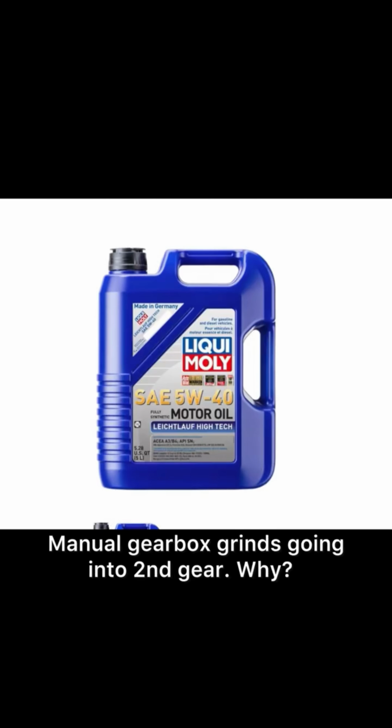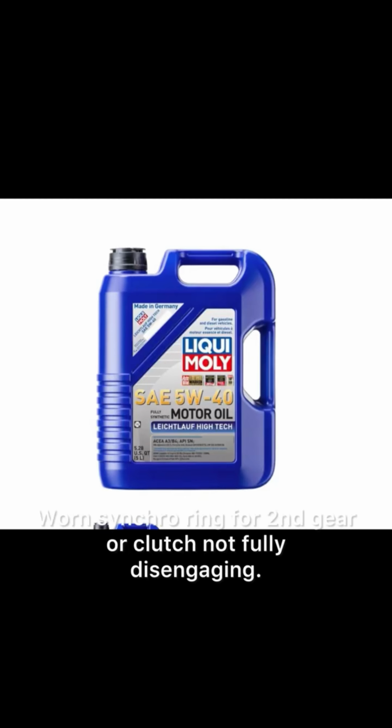Manual gearbox grinds going into second gear. Why? Worn synchro ring for second gear, or clutch not fully disengaging.